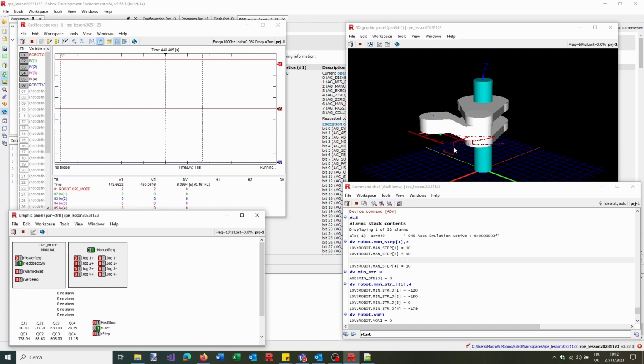Points could be outside of the task space, or even worse, in order to reach them, you can pass through some singularity of the system. That's according to your robot model, of course. Or remember, if you are in a point behind the robot, now let's go again to Cartesian. If, for example, you go here, which is behind, and from this point I want to reach a point here where I have the mouse.